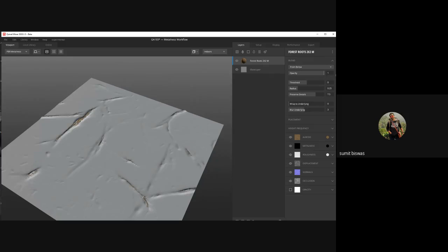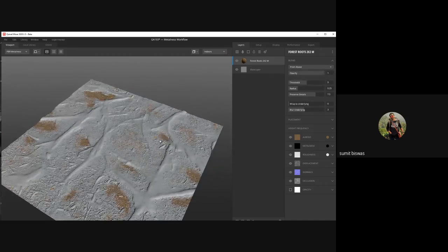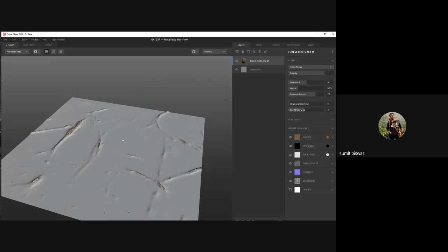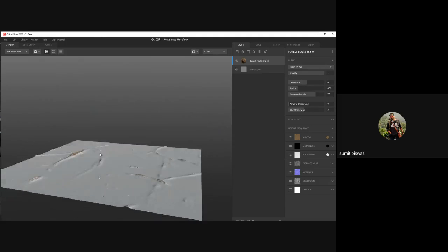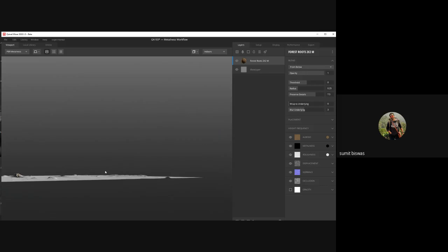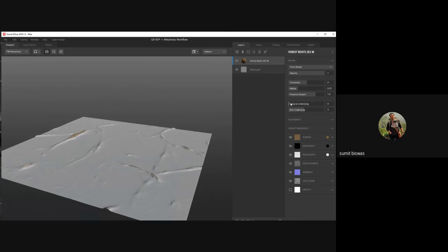Opacity, I can reduce, increase. From below, from above, I can change from which direction to read. So from below, basically, it's on the ground, so all these parts will be extruded outside, and whatever thing you can see here, it's part of displacement map. Then styling, you can increase this underlaying. You can see there's so many detailing and blur. You can reduce blur, wrap it nicely. Threshold you can increase, decrease, like it's below ground, above ground. You can decide with that.